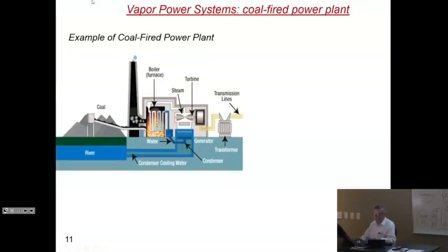So this is your classic coal-powered plant. You have a stack of coal stored outside. You have the boiler, which is really the vapor, the steam generator. I'll tell you why in a minute. The gases go up, the flue gases go out the chimney, and then the water is here. It goes through a set of heat exchangers and is transformed into steam.